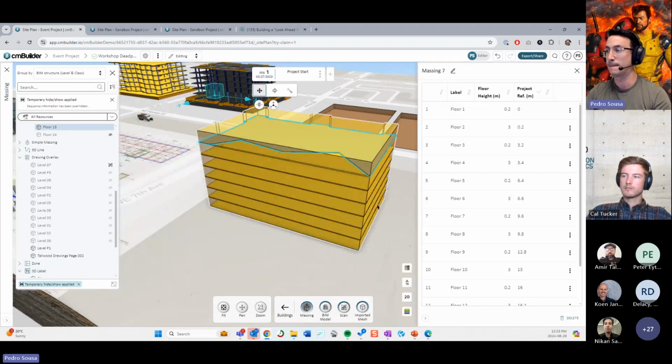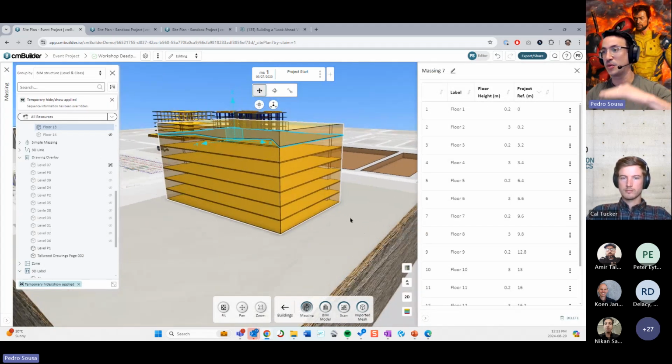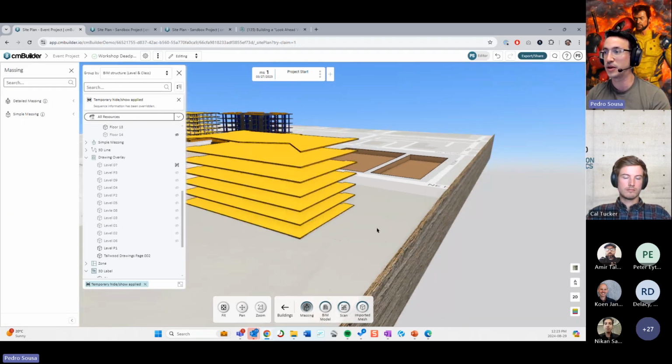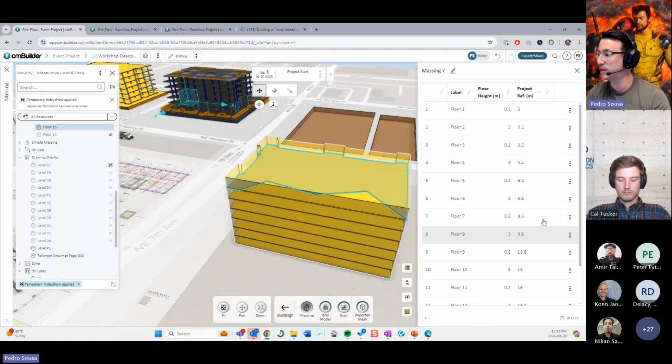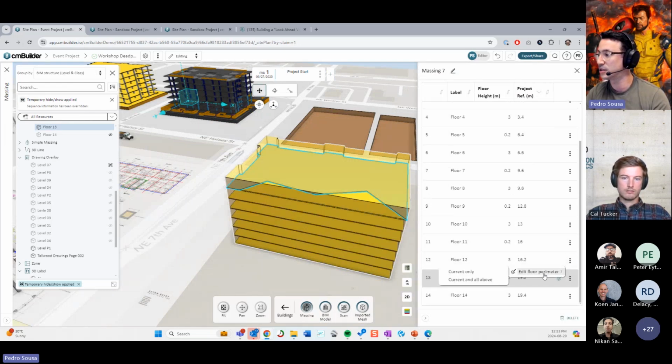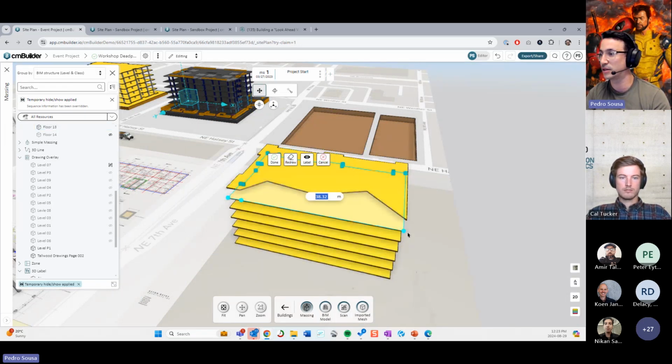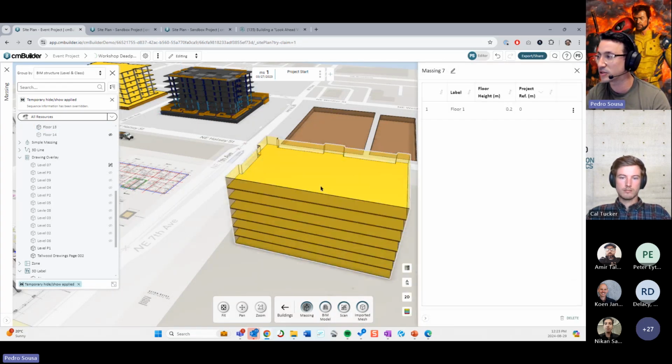However, the reason why I said that you can create the double floors minus 1 is because the top floor over here, you're not going to use it for anything, right? So instead of 14 levels, you do 13 levels for a building with 7 floors. Cool. So now you have all of these slab edges over here, and let me just redo that shape over there because this looks super weird.